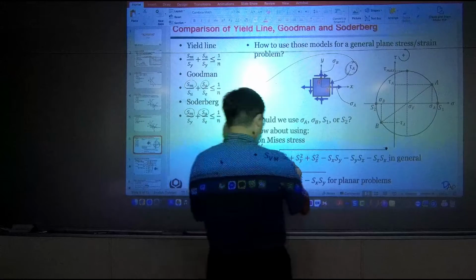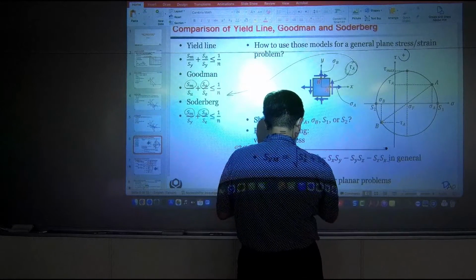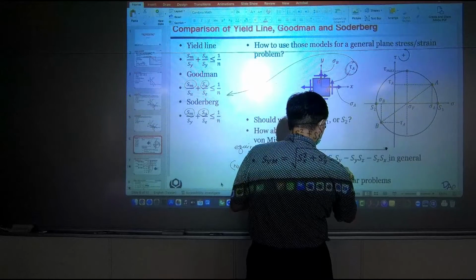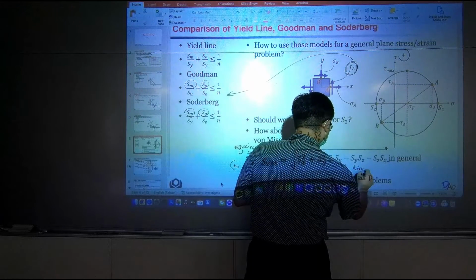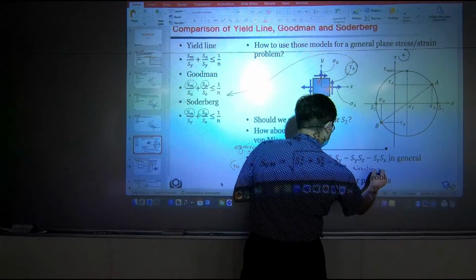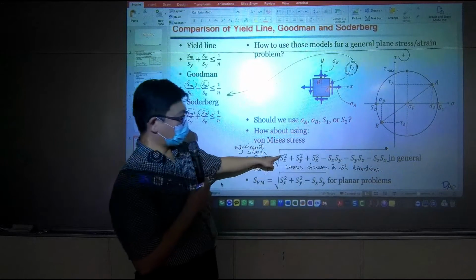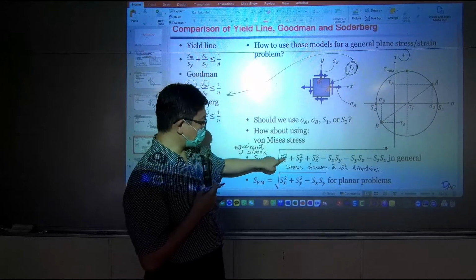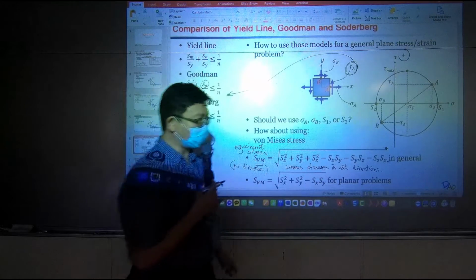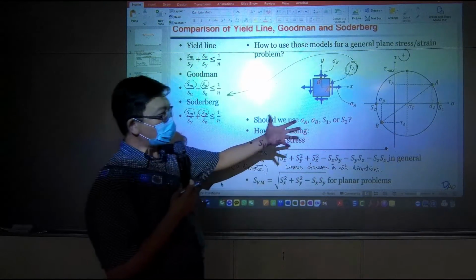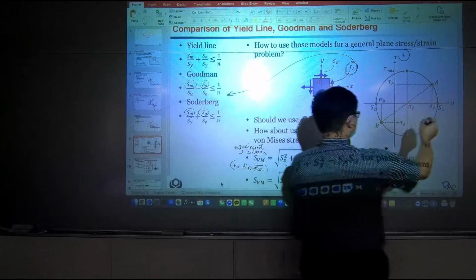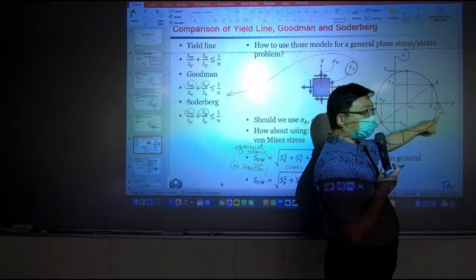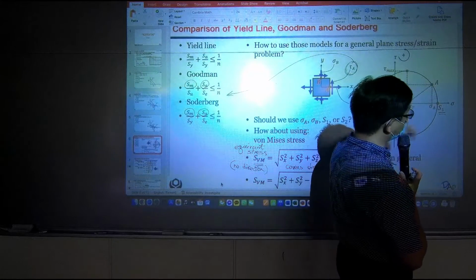And it covers stresses in all directions. Like here, it covers the stresses, principal stresses along x, y, and z, all directions. If you can draw a Mohr circle, if you can calculate the principal stress, it covers the information about your shear.